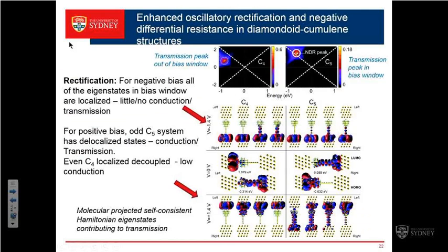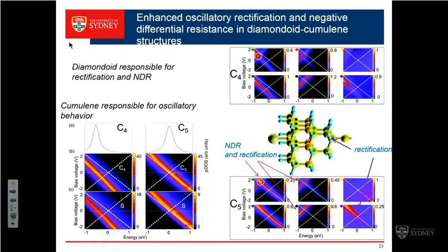Again, as I said before, you can pull apart and analyze where it's coming from, and you can even locate on your particle which atoms are responsible for the rectification behavior and which atoms are responsible for the nonlinear differential resistance. They're color-coded, so you can plot these curves for each atom. For example, the green is on this layer of diamond atoms, the blue is for this result, and so on. So you can analyze what is responsible.